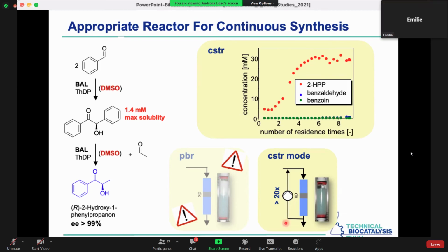Because you're working with the immobilized enzyme in the stirred tank reactor, you have this problem with diffusion limitation because of no convective flux on the surface of the particle. Right. So thank you. It would be better to operate it like this with immobilized enzyme. Did this answer your question? Yes, it does. Okay, thank you.